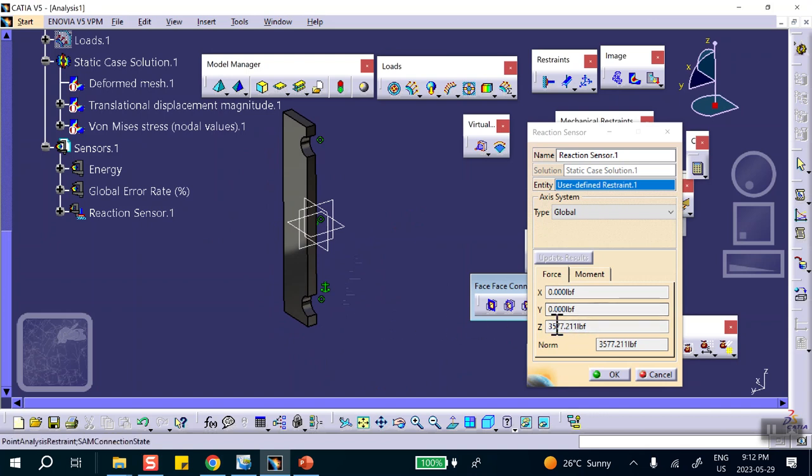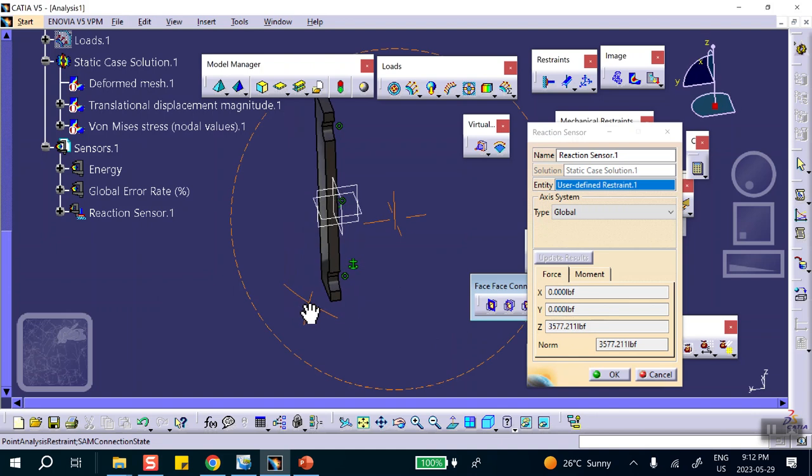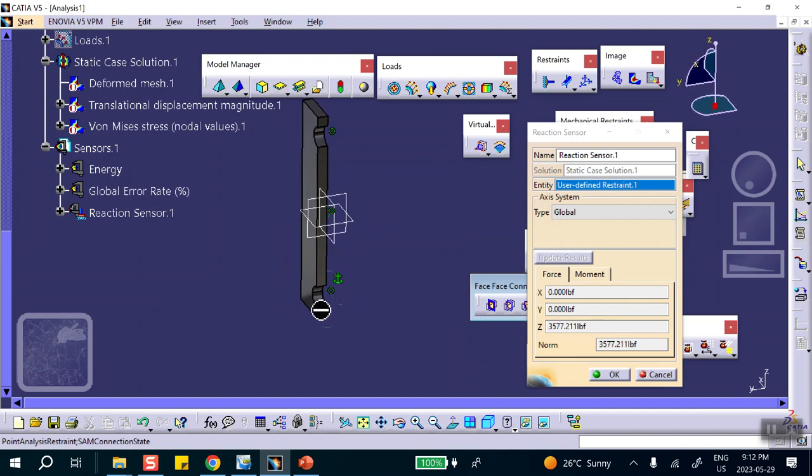we have to take this and we have to multiply it by 4. And that should be the same as what we got without any planes of symmetry. Now, I can't remember what we got without any plane of symmetry, but remember, I don't have any confidence in any of these numbers because we haven't done a mesh convergence study. But if you believe this is true, you have to multiply this thing by 4 in order to get the actual load. Okay, because this is the load for this 1/4 of the sample that we have modeled.